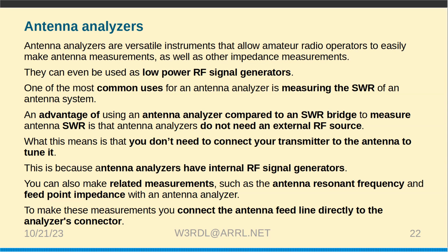And you showed that board last week. Yeah, the little nano VNA board. Actually, this was from Amazon. I think it was like $10. And it came with a couple adapter cables. It's called an RF demo kit. And you can actually calibrate. It's got short, open, and load on it. That's worth its weight in gold right there. And a through. It's got attenuators.